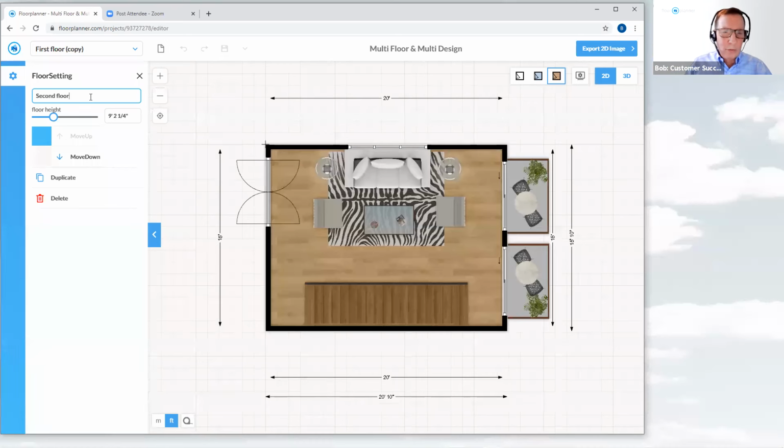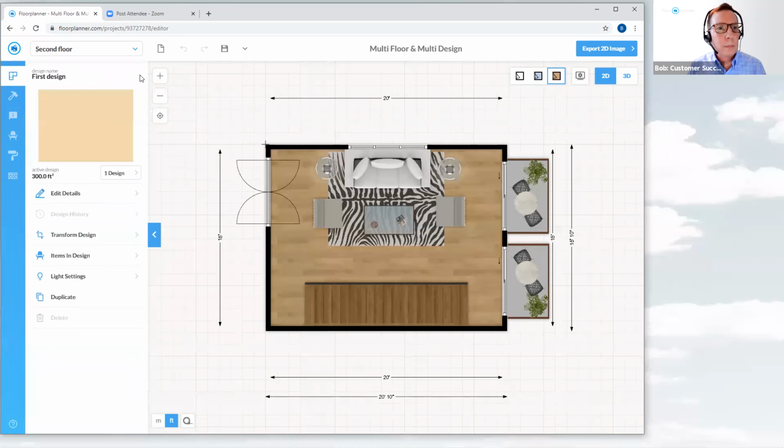Now, this is the second floor, and you can visually see with this new editor window over here on the left-hand side, there's the second floor, there's the first floor. So if you want to move this floor in location below the other, you just push it down. Well, for right now, we know it's the second floor, so we do want it sitting actually above as we had. And at that point, everything's in place. I'm gonna hit my Enter tab, and everything should be good. Let's go ahead and close that out. Hit Enter, close. Okay, now I'm gonna hit Save, make sure my file is saved, and see up here in the upper left-hand corner, we've now created two floors.